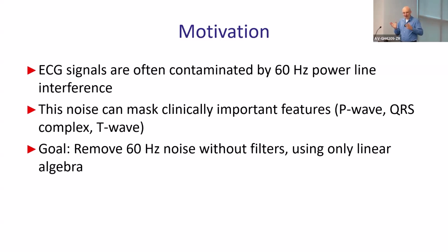We don't know the amplitude, we don't know the phase exactly, like how it is shifted compared to your recorded signal, because you start your recording not synchronized with the outlet, obviously. So how would you remove that kind of signal? You can filter it, you can use notch filters, which filter a particular band of frequencies around 60 Hertz, like from 59 to 61, for example. A very narrow filter, which is kind of killing that particular frequency.